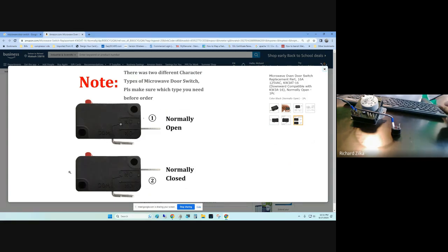And I have a switch here open so I can show you guys inside. Now this one here is a normally closed switch. Why? Because they moved the pin location where you can connect the wire to the top instead of the bottom. And then they have the switches that may have one here, and here, like 3 places to connect. That's normally open and normally closed. We call that a single pole double throw switch.